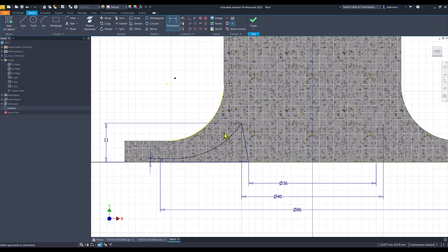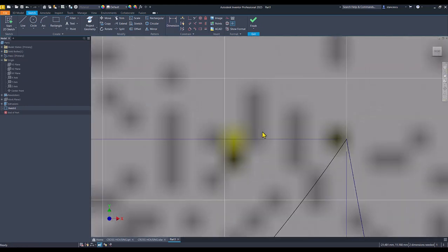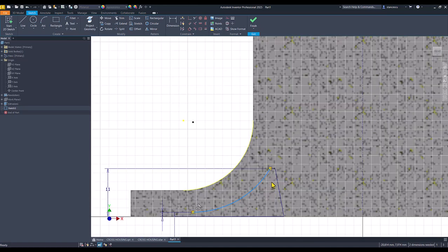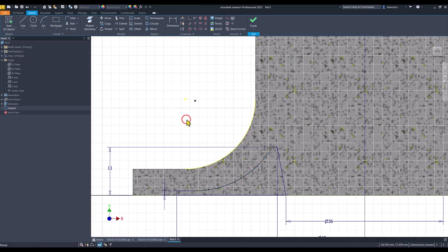and now we see that we can move this arc to the left at our will. But I mentioned that this point is the center of both. So let's make concentric. This one with this one. Yes.